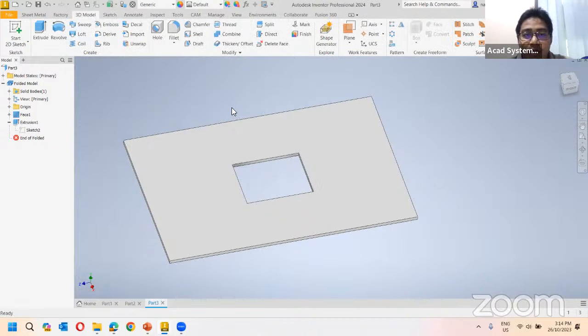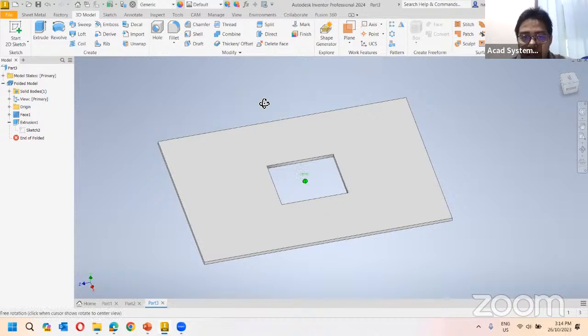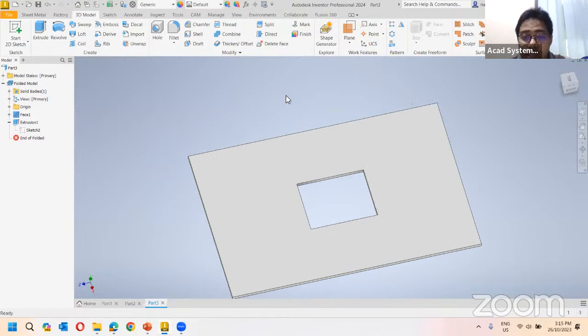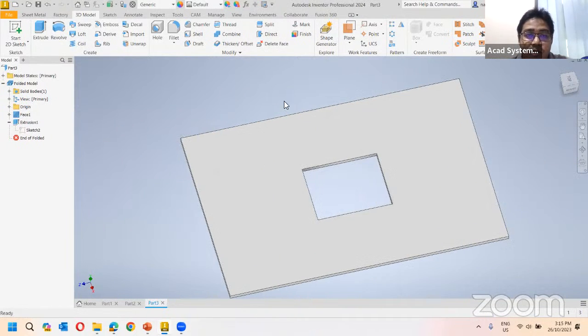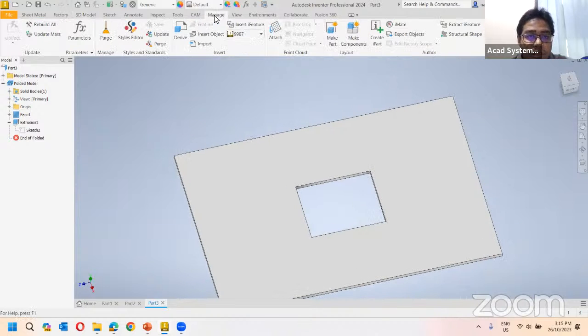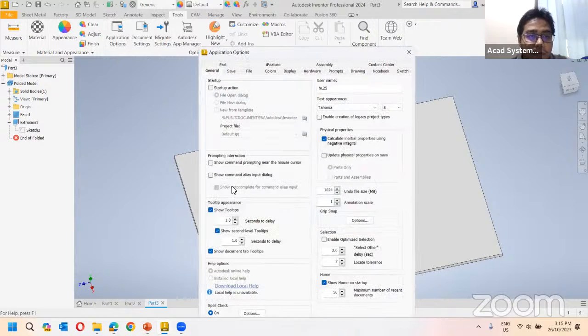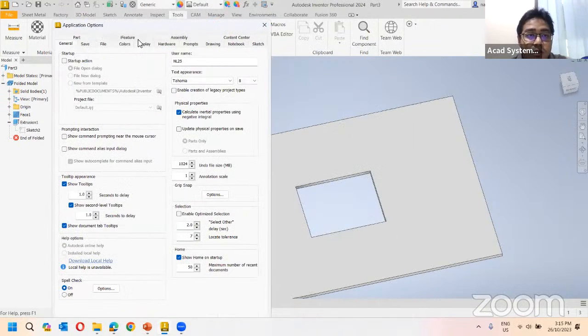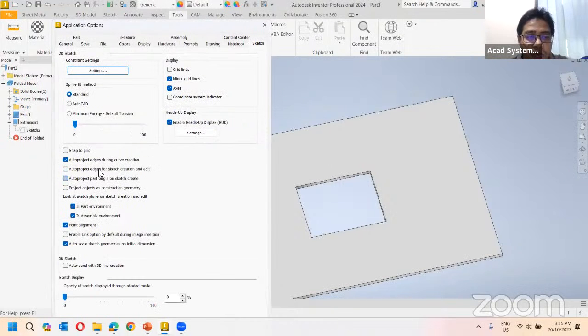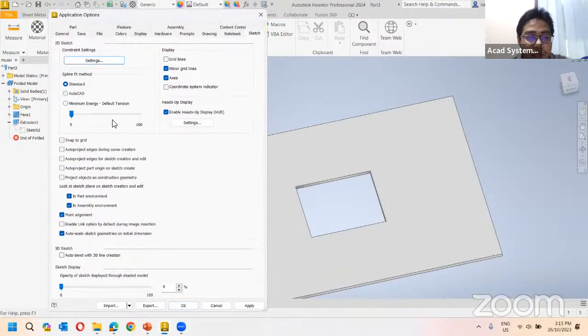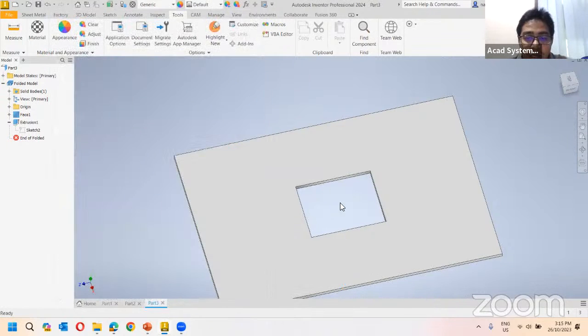It usually will be done automatically, but since this is quite important, maybe I would like to create my project geometry manually. So I'm just going to turn off the auto project under the tool here, and I can select my sketch. Actually, you don't need to turn it off, but it's better to turn it off, just in case no other automatic project is included.